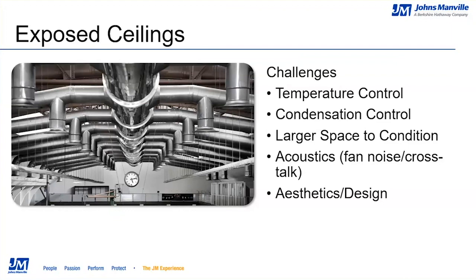Exposed ceilings create unique challenges. First and foremost is that it creates a larger space to be conditioned, which can be a drain on energy efficiency. If we look at the ducts themselves, they often need to be insulated for a variety of reasons. Temperature and condensation control, due to the variance between ambient air and the air moving through the ductwork. Acoustics, such as fan noise and crosstalk, and aesthetics and design.